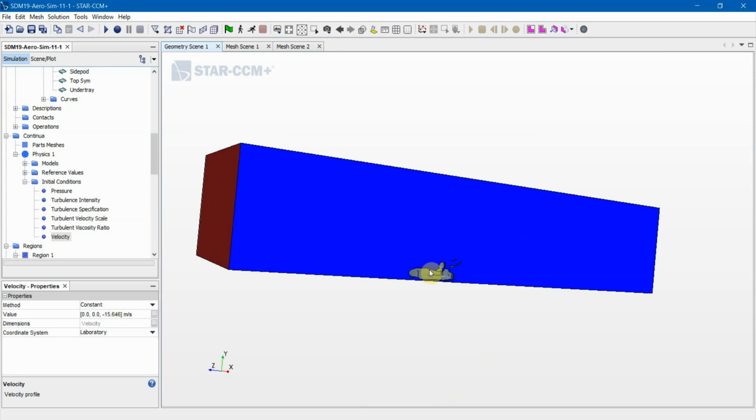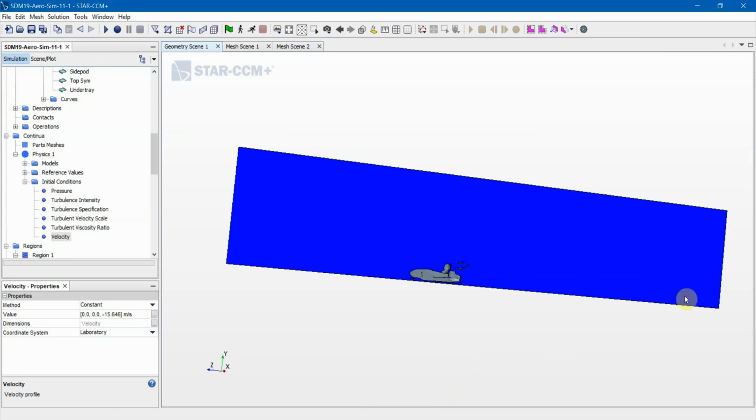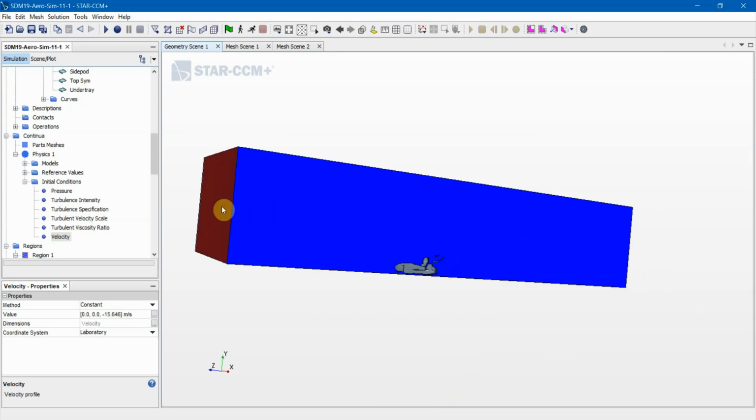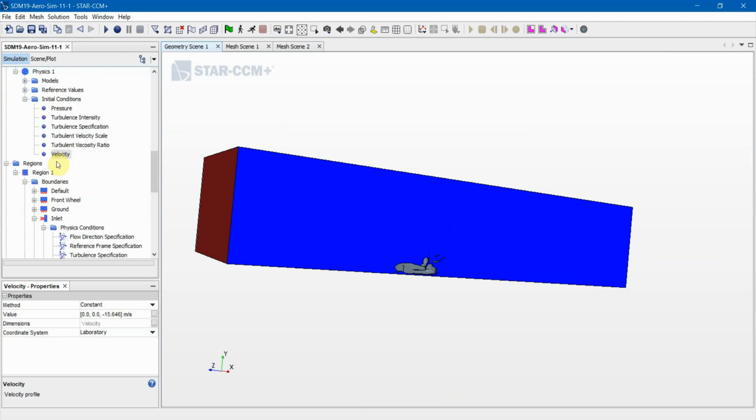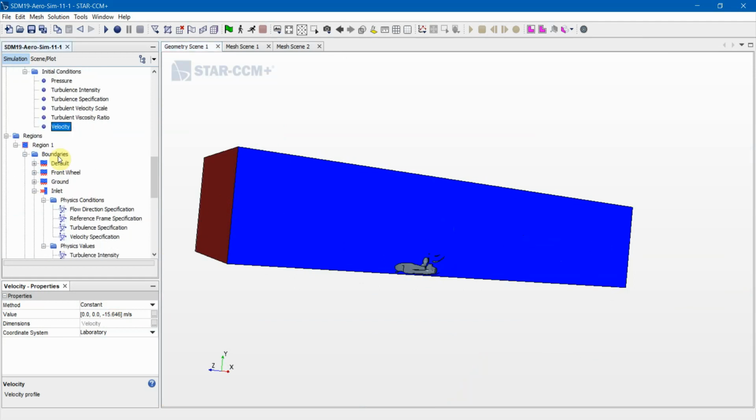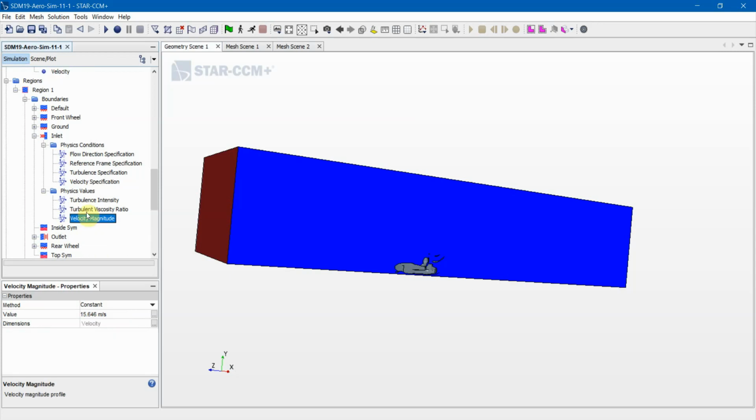So you'd be wasting time computing that, whereas you can just make everything 35 miles an hour, and by having the inlet give 35 mile an hour air inwards, it's just sustaining that initialized air. So don't forget initial conditions, that's important. Almost forgot about that, my bad.